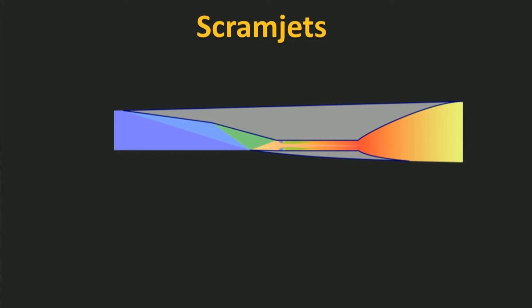Here's a simplified cartoon of a cross-section cut right down the middle of a simple scramjet-powered vehicle. It's not the X-43, but it's a simplified arrangement and one that's amenable for us to analyse. The air comes into the engine from the left. We call this part of the engine the inlet, or sometimes the intake. As we noted when I introduced scramjets, in the inlet the air slows down and its pressure and temperature increase.